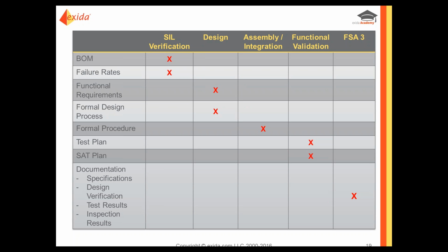One comment, or one question, is that it's not always possible to get the failure rates for all the components, and I think the person is saying that 90% of the time we don't have them. That's true. And I did make a note that I could put some of those on the website, just for the generic parts you need to consider in a valve assembly. We do have a site, silsafedata.com, where we've begun to post some generic data for devices, and we can add these components to it.